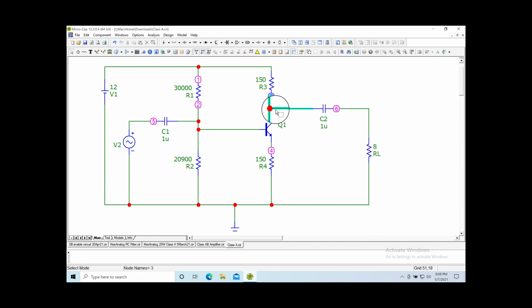If your source impedance is not low enough, you're loading it down. Well, what is the source impedance? If you're standing here at the capacitor looking into the source, which is this node, you have a 150 ohm path. And this path, remember, this impedance is very low, so this path goes down to ground. So you have 150 ohms to ground, and you have a transistor. Now let's say the transistor is fully on, so there's very little impedance. So best case scenario, you have 150 ohms here.